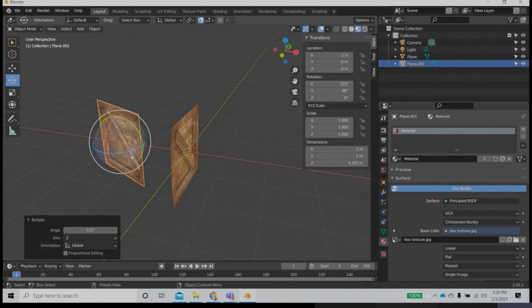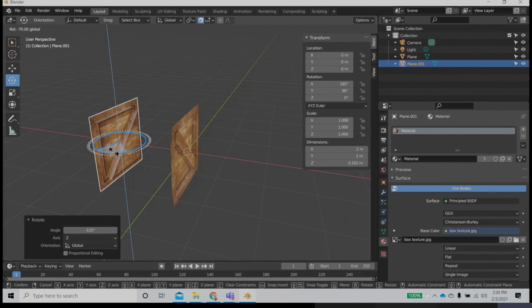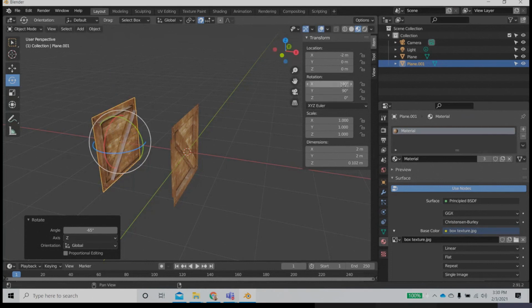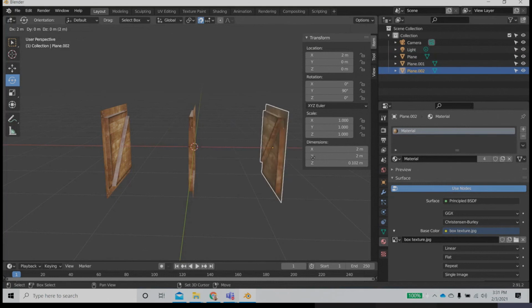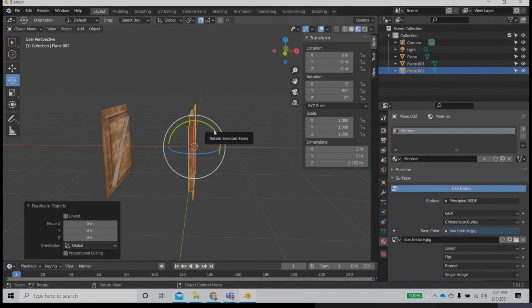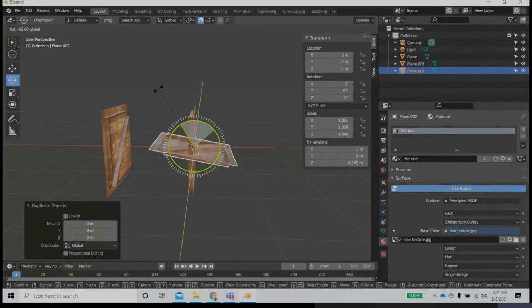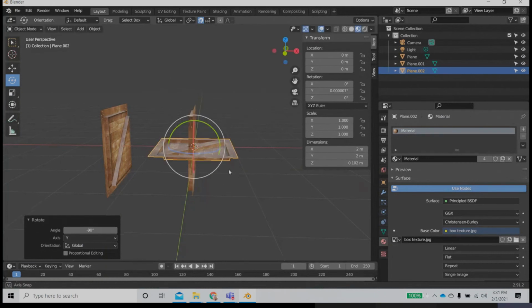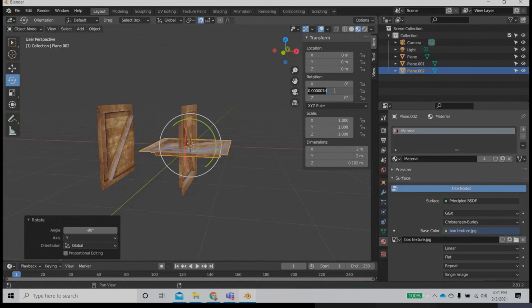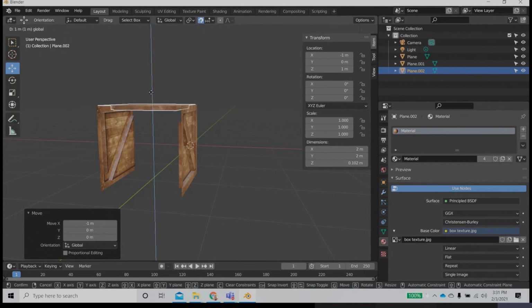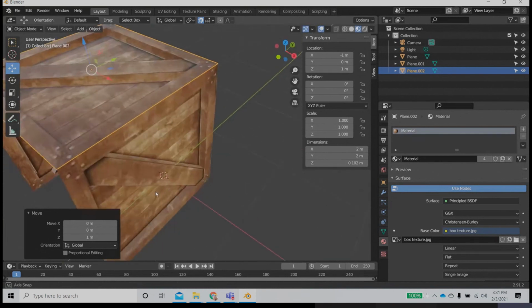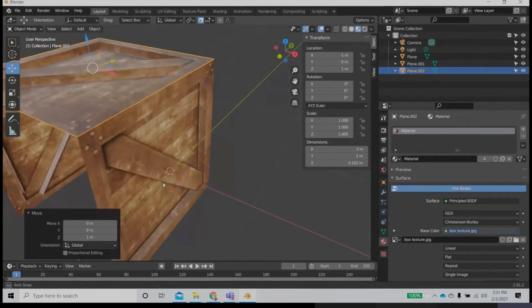Okay, and then see it is 115, an increment of 5, so we can stop at 180, or you can type 180 here. Okay, then I'll select this, Shift D, right click, and rotate it until it becomes... why is it not exactly 0? And then it has to be moved. And now it has snapped to exactly the right location.